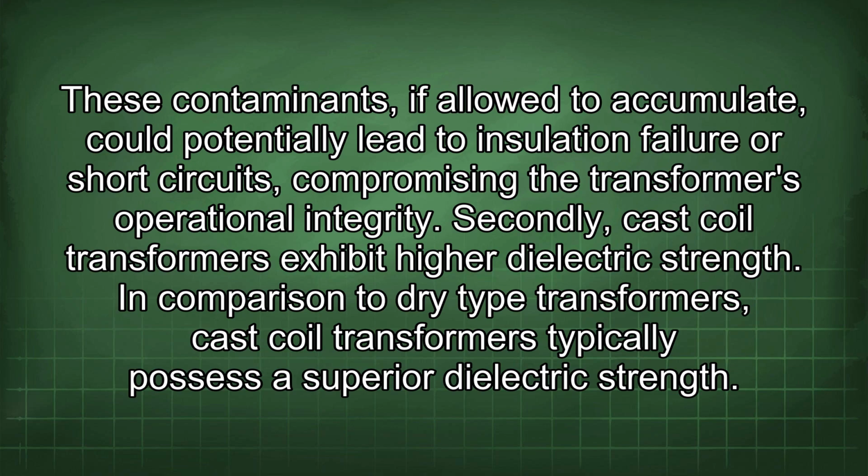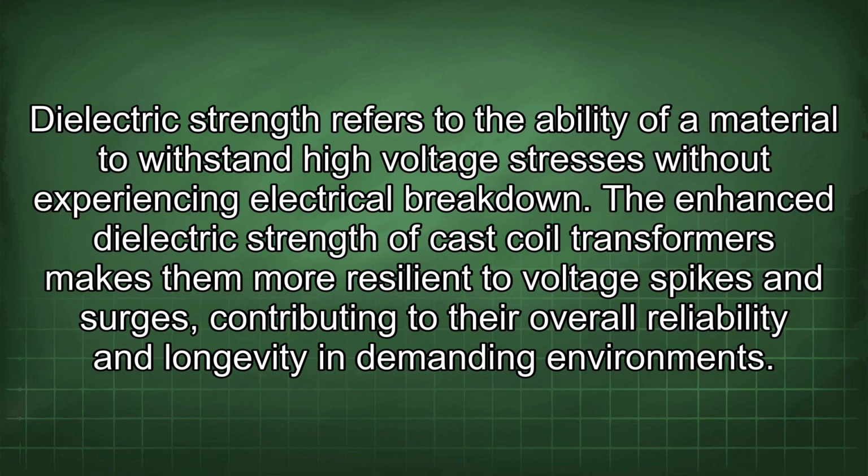Secondly, cast coil transformers exhibit higher dielectric strength. In comparison to dry-type transformers, cast coil transformers typically possess a superior dielectric strength. Dielectric strength refers to the ability of a material to withstand high-voltage stresses without experiencing electrical breakdown. The enhanced dielectric strength of cast coil transformers makes them more resilient to voltage spikes and surges, contributing to their overall reliability and longevity in demanding environments.